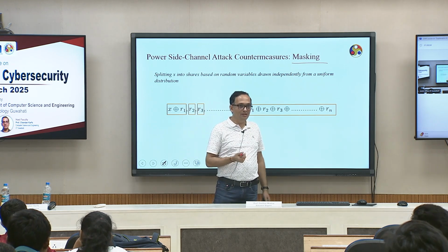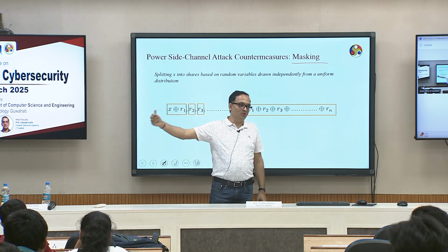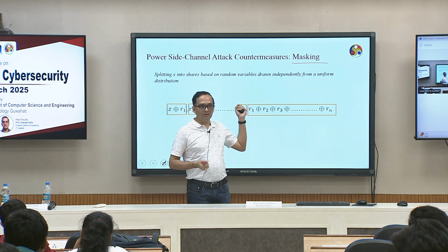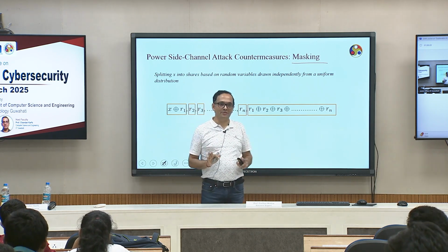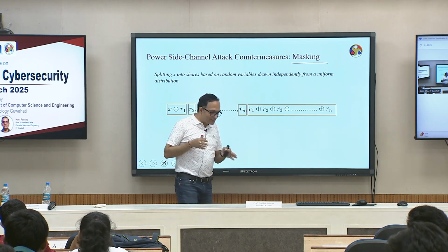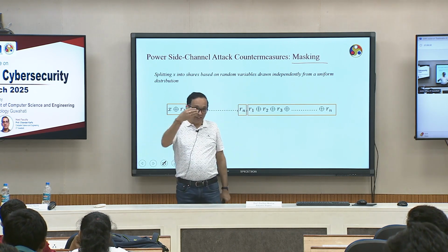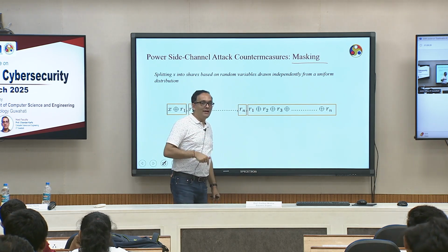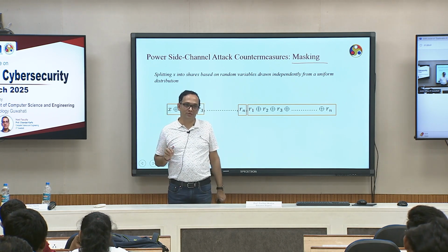as well as area. How do you balance between, say, probably I do not need to protect it completely, right. So, if you make sure that people cannot break it within 1 million traces, so we are just talking about 10,000, 12,000, right. If you take 1 million traces and still you cannot break it, it is kind of safe, right. People do not have that much energy to go beyond that, right. So, there is a trade-off between the security level versus the area overhead, and specifically for IoT devices you should have a trade-off between this, right. So, in one of my talks I will talk about what the trade-off is and how you get a good protection with comparatively less overhead.